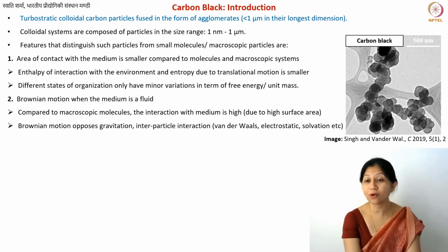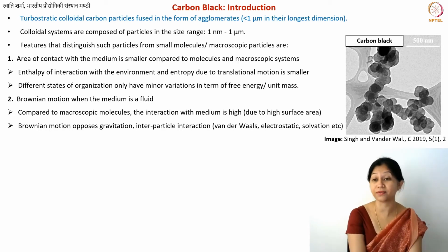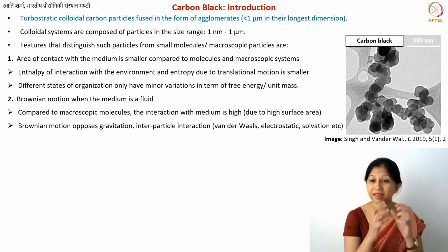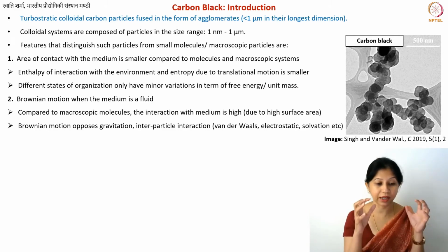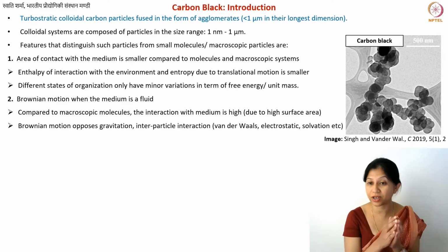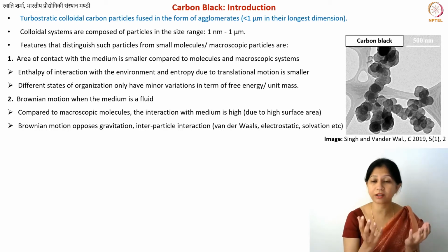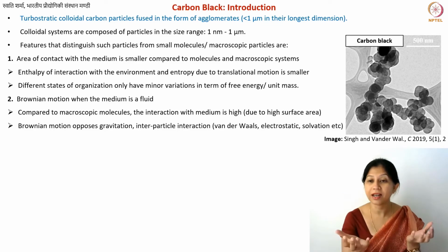And that is why the low density is also very important. The light weight of the carbon is also very important. This entire material is also called a fluffy carbon material, because it is a very fluffy, spongy material altogether, even the individual nanoparticles, because they have only a short range order. These are very small turbostratic crystallites, which may contain a lot of defects and some impurities, and the weight of the individual particle is also very low. And of course when you see a cluster, you can see that there is a lot of empty space, so to say, in that cluster.